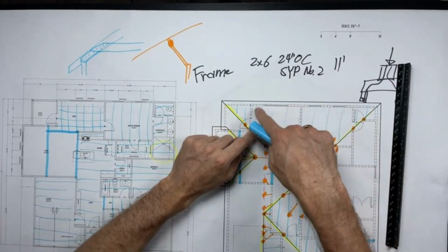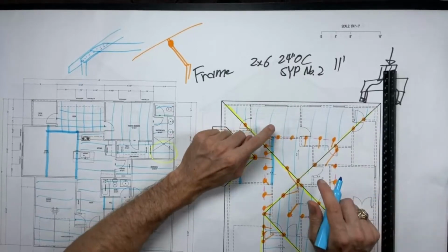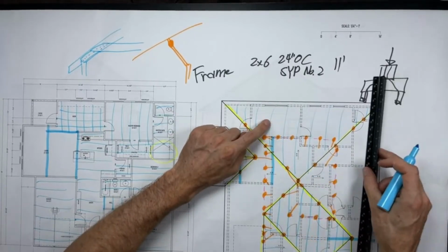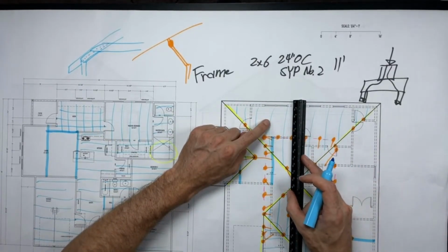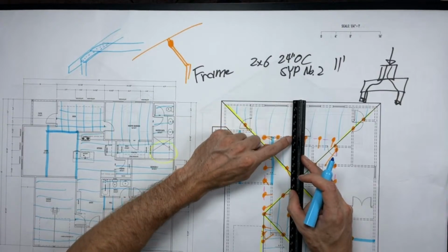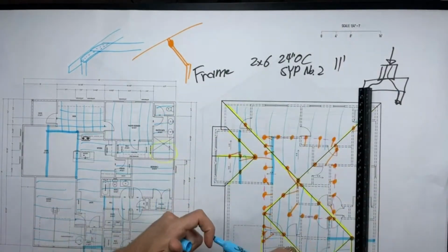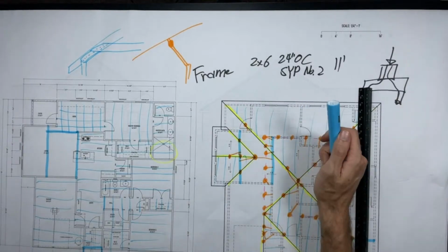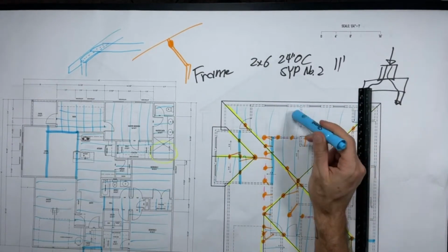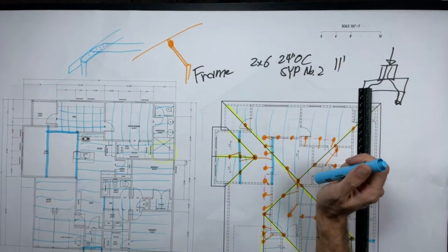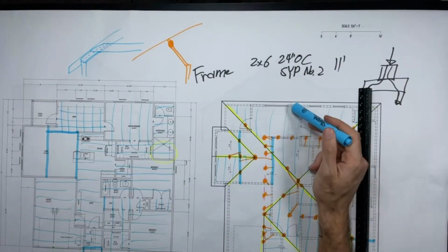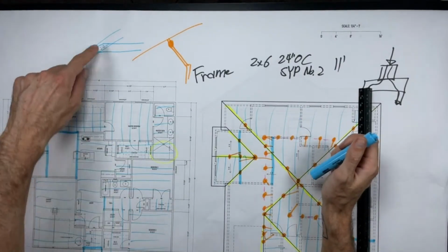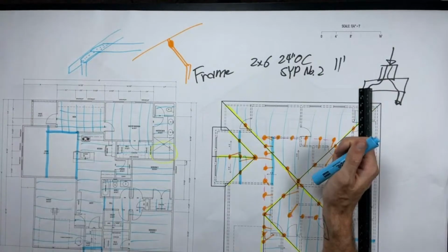So what does that mean? Right here in this room, these rafters cannot span 11 feet. I made the assumption earlier that they could. Well, what are we at? We're at about 8 feet to our first purlin support. I'm actually not that worried about it, because 8 feet's pretty good. That's a solid 60 or 70% of 11. So that's actually pretty reasonable for the little bit of extra weight, and this is not that big of a room.